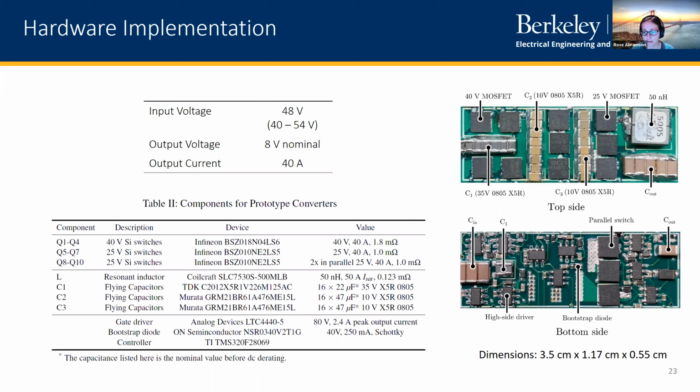And then the bottom side of the board shows the gate drive circuitry. So this was controlled using a bootstrap gate drive circuit, which essentially lets us connect several different gate drivers together using diodes and just power one chain of them. So that helps us get rid of a lot of things like LDOs and level shifters and isolators, and really helps compact the total area.